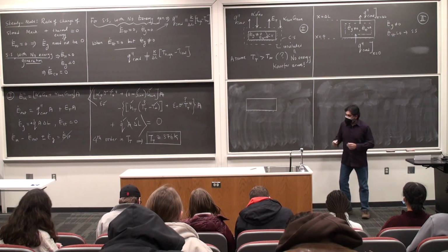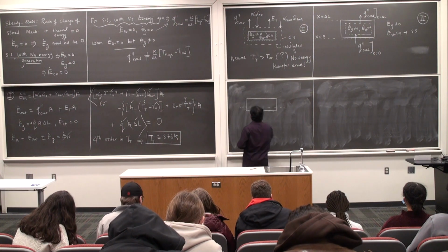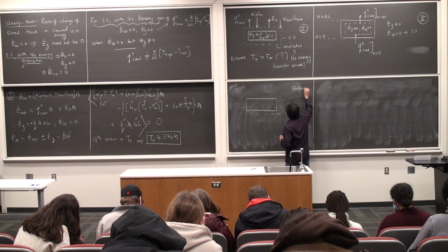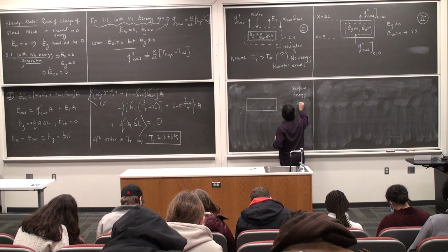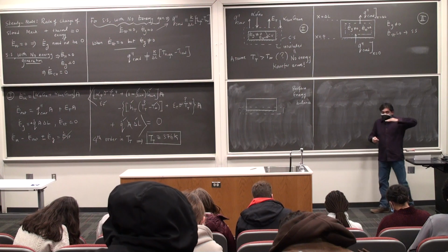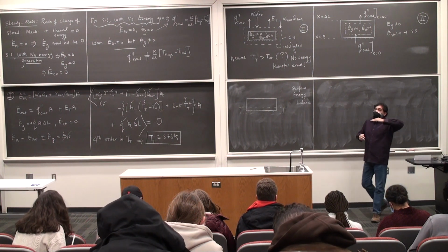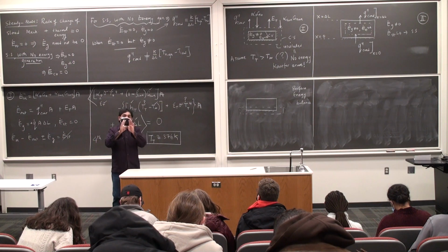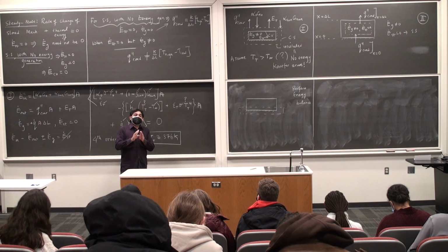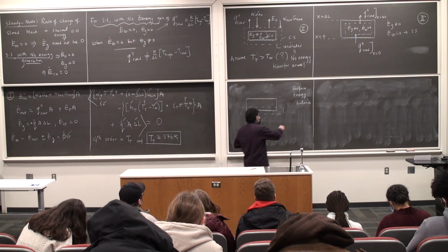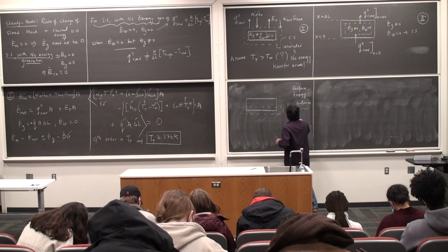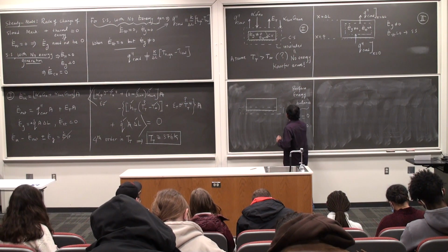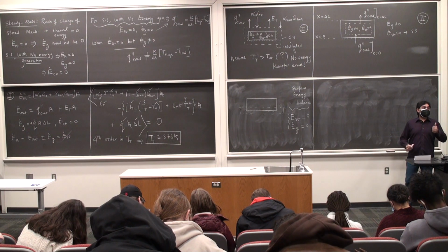Let's take a look at this bottom guy as the more interesting of the two. This is surface energy balance. Which means you are interested only in events taking place at that particular surface, which means that if you are doing surface energy balance, even if there is energy generation within the control volume, for your surface energy balance at that surface, E dot g is 0. I want to be very clear about this. For any surface energy balance, there is no volumetric phenomenon that will be taken into account. You will have only surface phenomena, things that are going out, coming in, and so on.